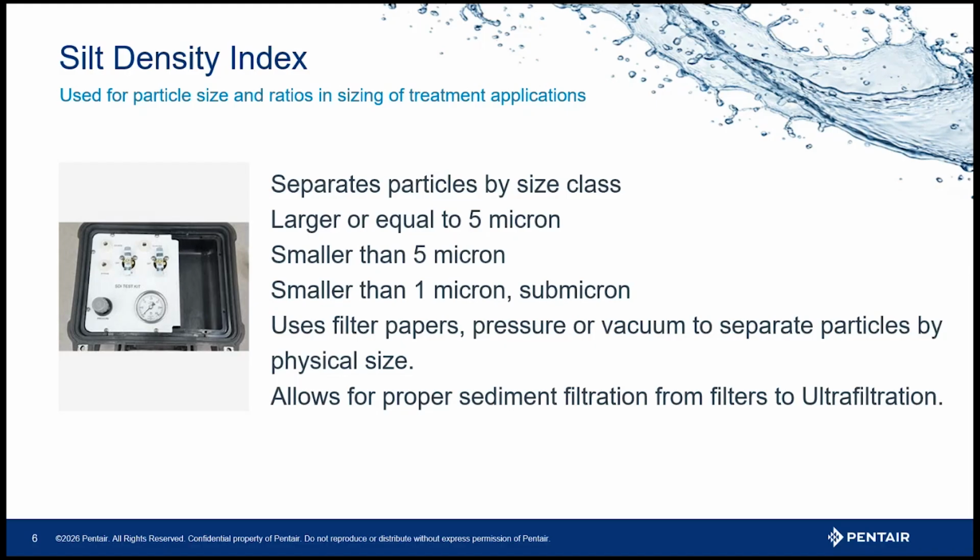So the summary of the process: take a raw water sample, let it settle for 5 minutes. Large-scale sediment will fall out of the water column. Decant the water off the large particulate, that's pour it off in chemistry terms. Run a turbidity test on that water. How much turbidity do you have?